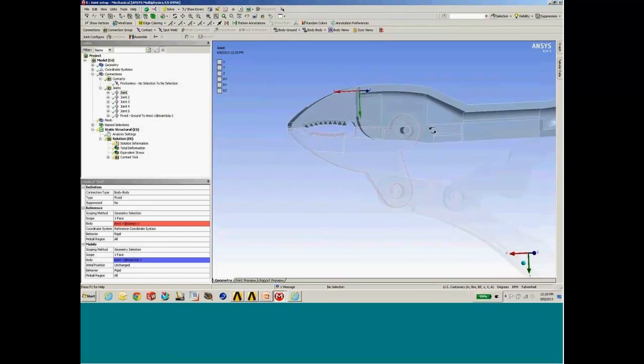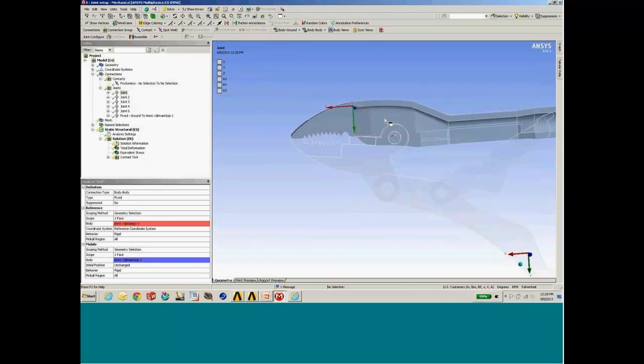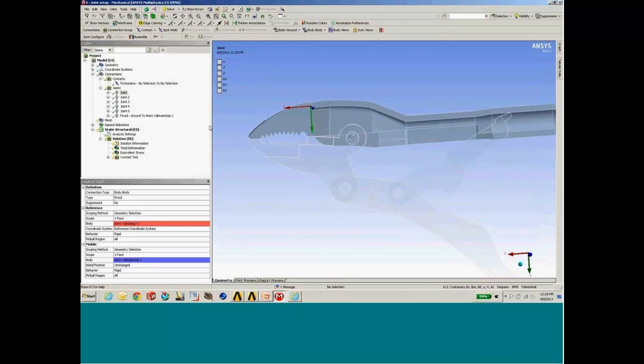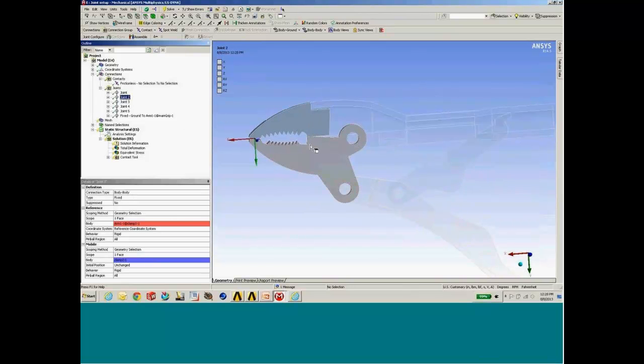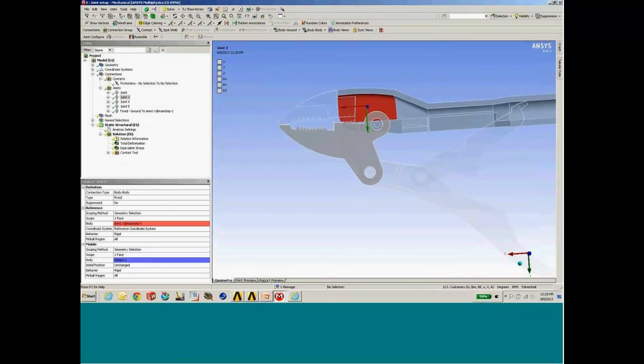Now in this case, I've got two rigid bodies highlighted on the top. They're currently fixed together, so that's going to act like a welded connection between those two bodies. I'm going to keep that one. That one's a good one. Come down to here. Well, I've already got a contact region defined between these two bodies, so I don't need that joint. I'm going to delete that like I would an unneeded contact region.